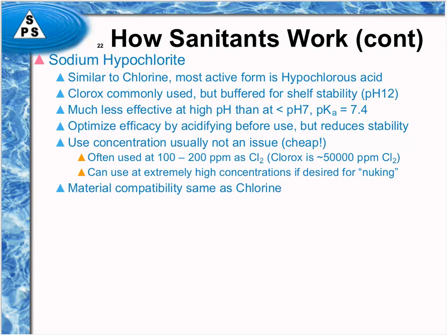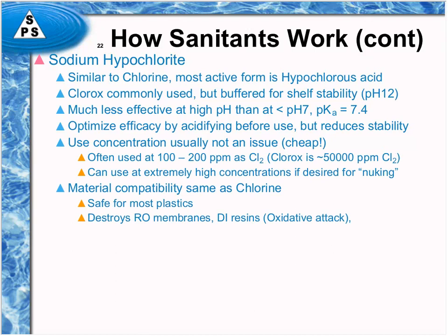The compatibility issues are the same as with chlorine. It's safe for most plastics. It destroys RO membranes and DI resins. It corrodes stainless steel. It's not an oxidative attack, but a chloride corrosion attack on stainless steel. So you're going to find if you use hypochlorite in a micro lab, for instance, on your stainless steel tables and stuff like that, eventually you're going to develop what looks like little rust pits and rusty areas in the stainless steel, and that's from the chloride attack.